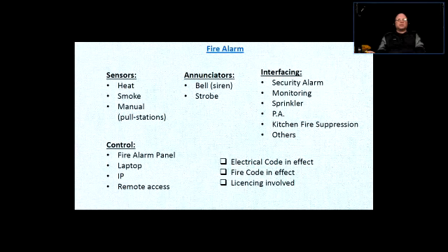Now, sometimes there will be false alarms. If the city water pressure goes down, and the pressure in the sprinkler system depends on the city pressure, and it goes below a certain level, then the communication of the sprinkler system can also trigger, notifying that the pressure has gone down.